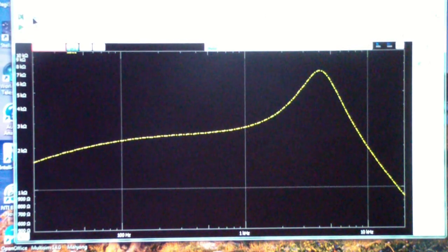And by the way, the reason that you hear a sound even with the speaker turned off is basically there is feed through the 33 ohm resistor into the speaker. So basically the 33 ohm resistor is in series with the speaker in one position and in parallel with it in the other. Okay, here you see that we have a relatively flat 2 to 3K out to a little past a kilohertz with the speaker connected, maybe 2 kilohertz.